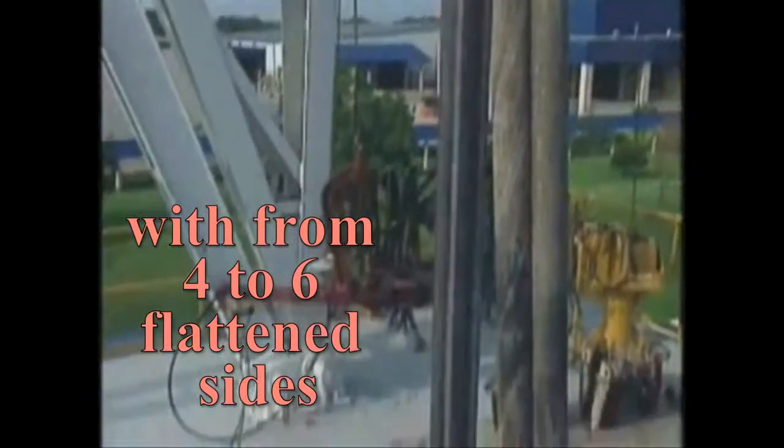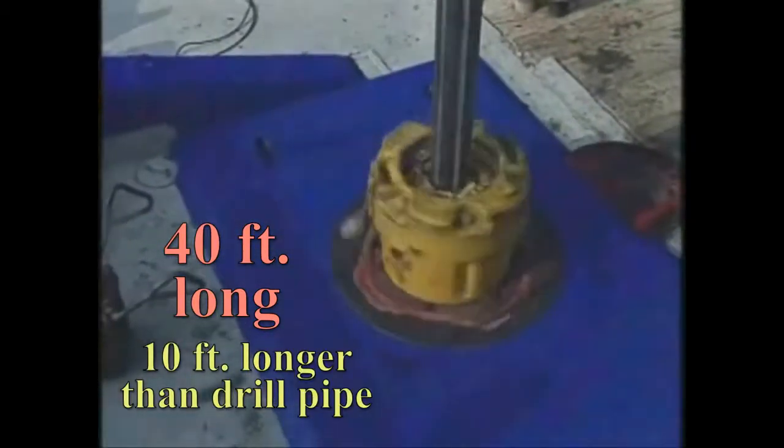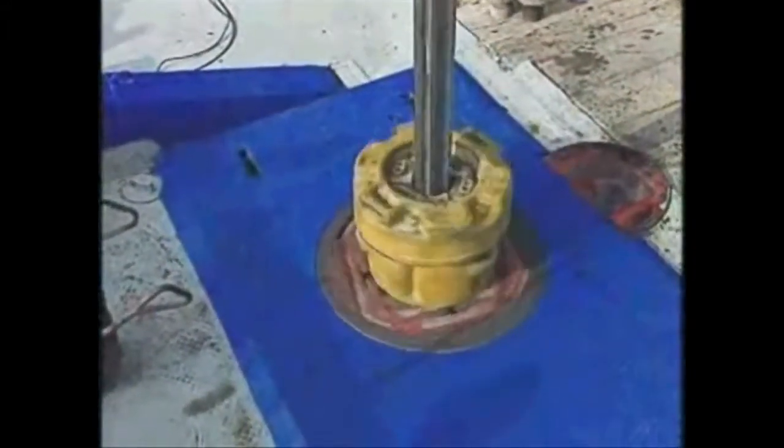The Kelly pipe is the topmost joint of the drill string with from 4 to 6 flattened sides and is 40 feet long, 10 feet longer than drill pipe. The Kelly or top drive transfers the torque or rotating power down the drill string to the bit, allowing the rock to be cut. Let's now examine the drill bit and its colorful history.